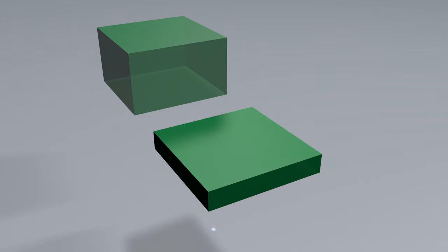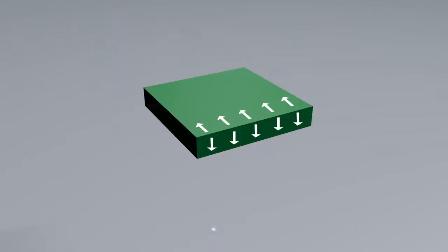Why don't we take a closer look at the shear stresses? Shear stresses on one side of an element are accompanied by shear stresses of equal magnitude acting on perpendicular faces of an element. Thus, there will be horizontal shear stresses between horizontal layers of the beam, as well as transverse shear stresses on the vertical cross-section. One very important point to remember: at any point within the beam, these complementary shear stresses are equal in magnitude.